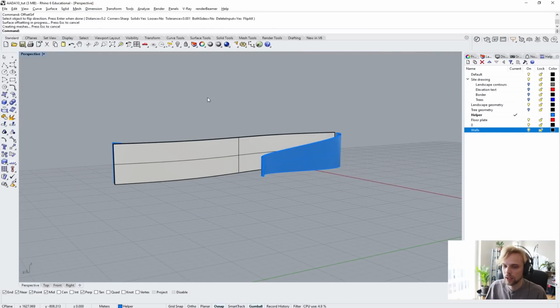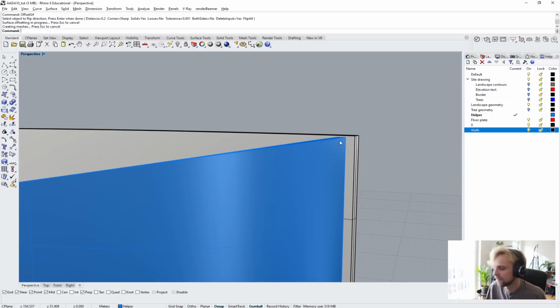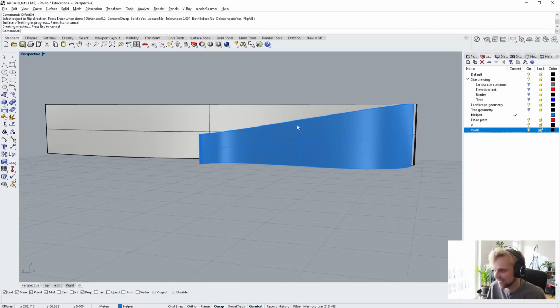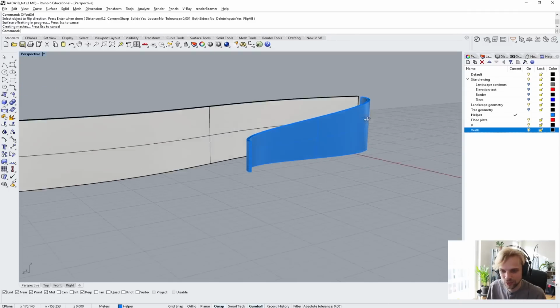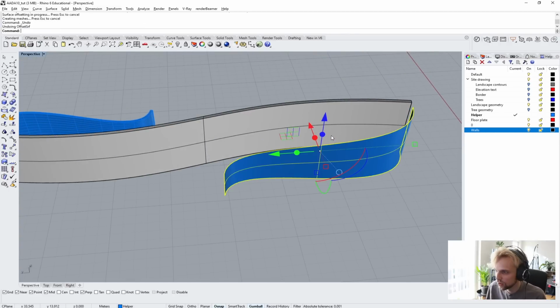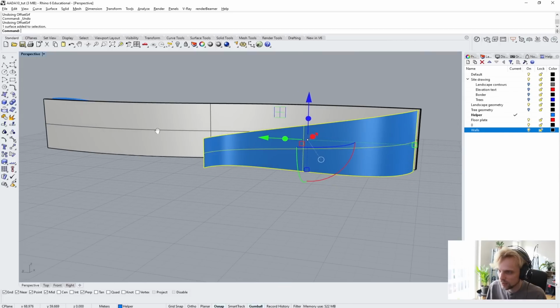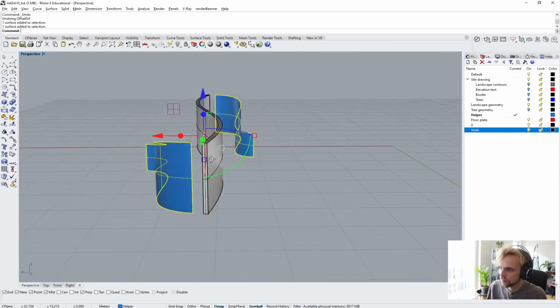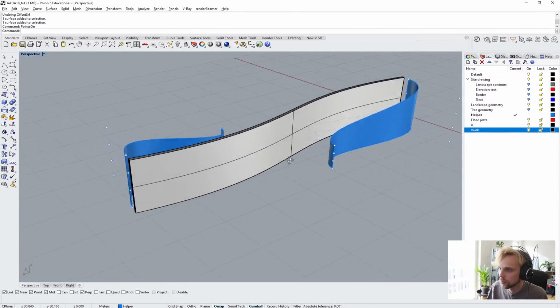That's nice. And now, actually I don't like this height. This is a little bit too high, because if a person is like 2 meters high, for a pavilion this is way too much, right? So I will undo, Ctrl Z 2 times, and I will just select these 2 surfaces here, and I will type in points on for them, points on.